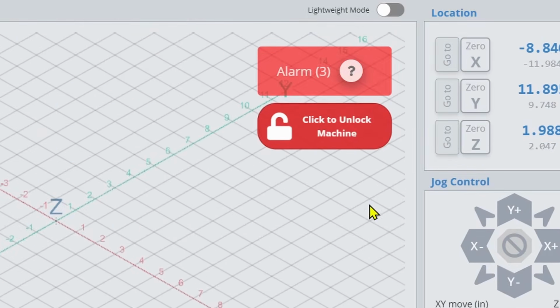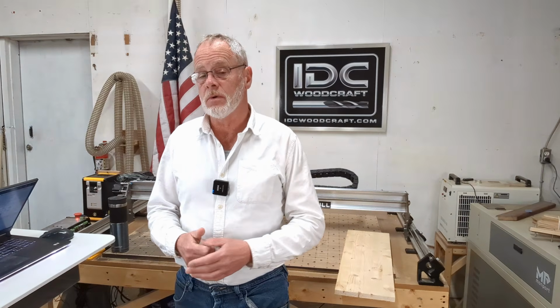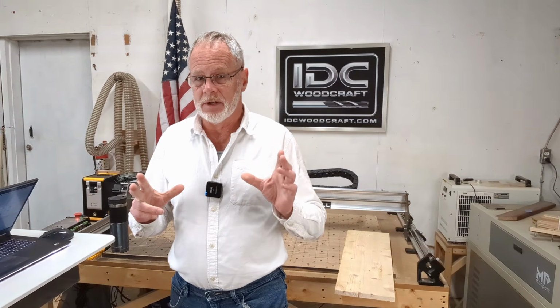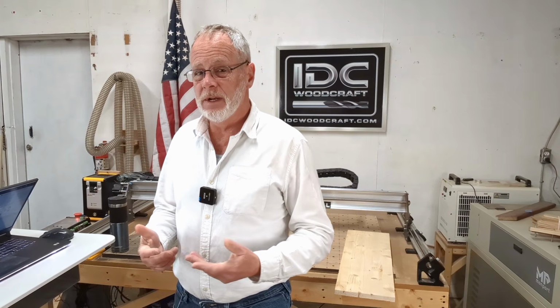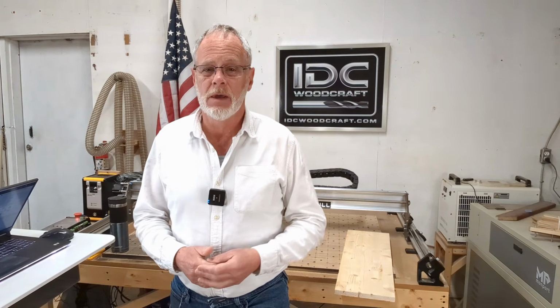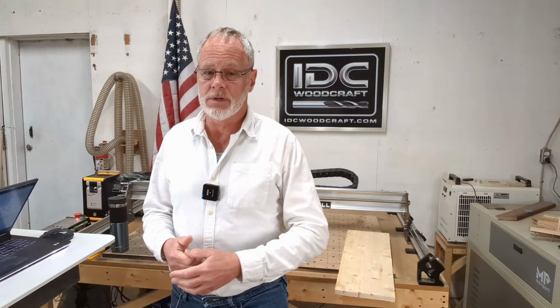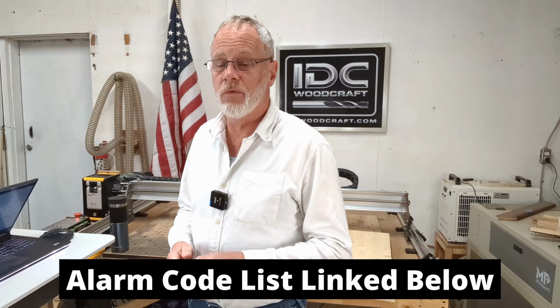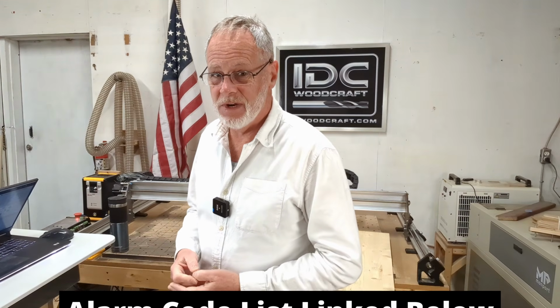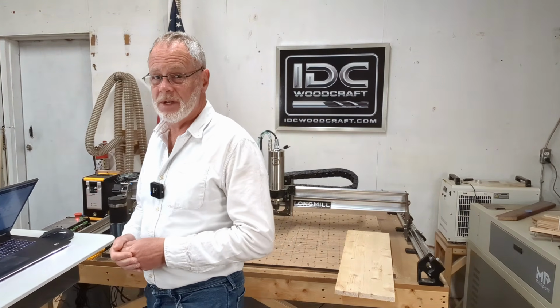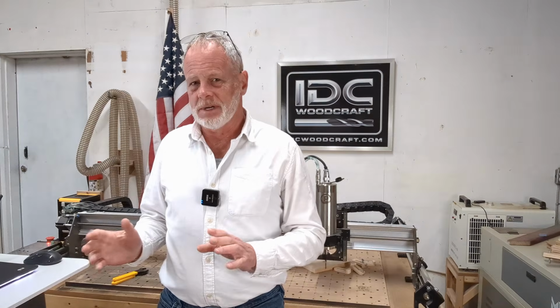Now I stopped it, and you see I got this alarm again. It's an alarm 3. So sometimes you may see this alarm feature pop up, and you're not sure what it is. I've got an alarm code list that tells you what each alarm code is. In this case, we just interrupted the cycle. If you want that list, down below in the description there's a download link for the alarm code list. I suggest that you get it because you will get alarms from time to time and you're not going to understand what they are.